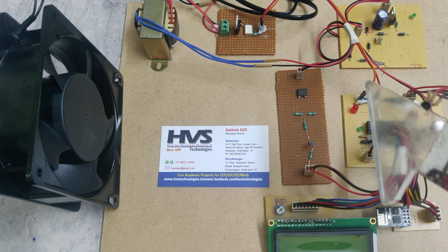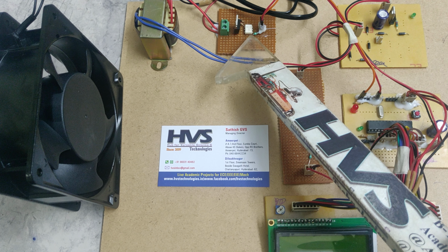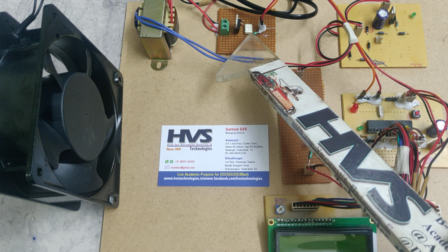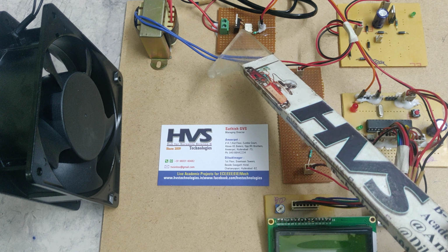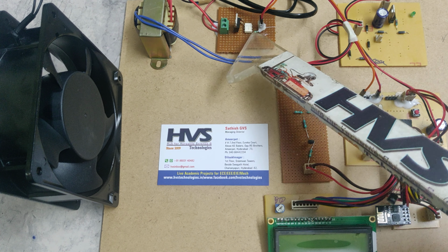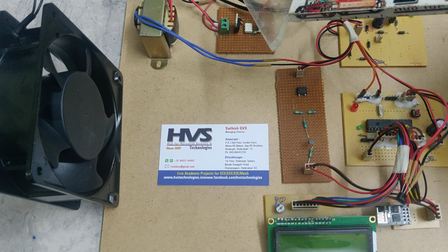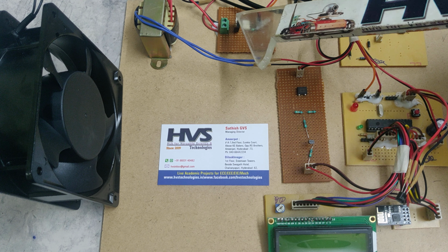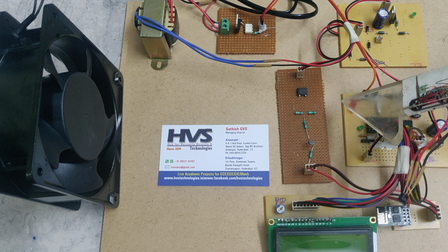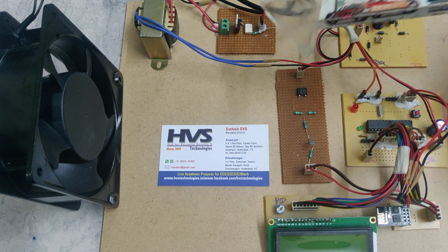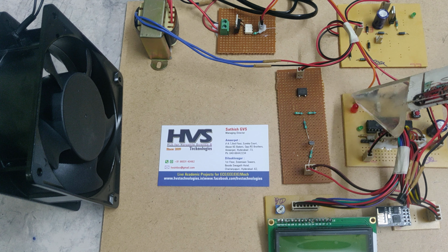So coming to the component wise board explanation. Here the triac board consists of a diac, that is an optically isolated diac. This diac will trigger the triac. So we are going to trigger the diac, and the diac will trigger the triac. Why? Because the triac needs an AC signal to trigger by itself. That's why, since the microcontroller can't provide an AC signal as it's a DC electronic component, the diac will provide the AC signal output to the triac whenever it gets the DC signal from the